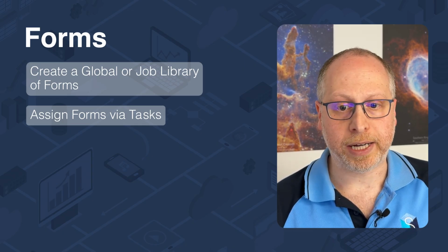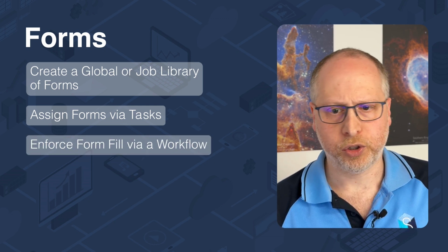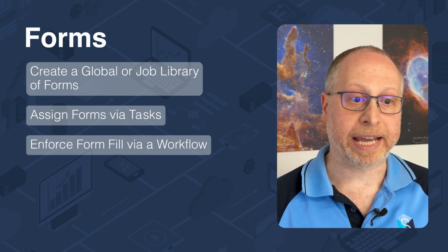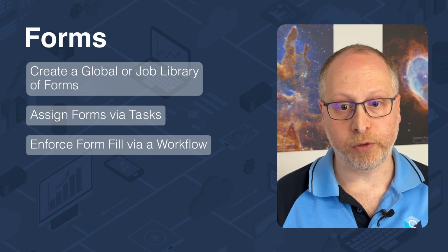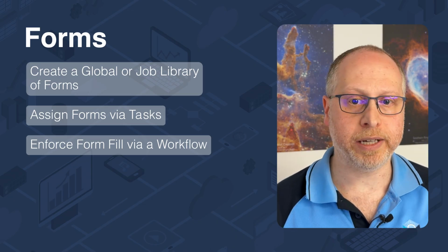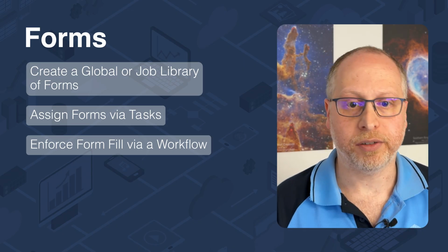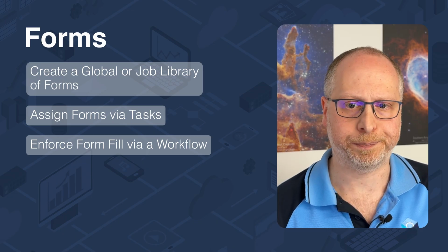You can also enforce form fill as you move through a workflow. So as you move through an ISO 19650 process or even just a CAD review process. So for example, if you move through in review back to WIP because there's more work to be done, you can have a form pop up and you have to fill that out to answer all the questions about why it's going back into the WIP state.